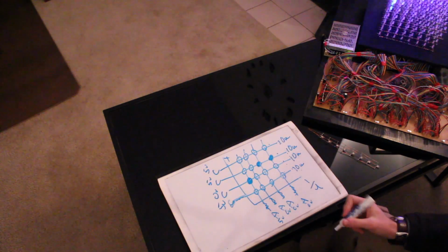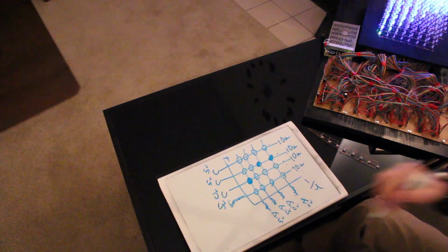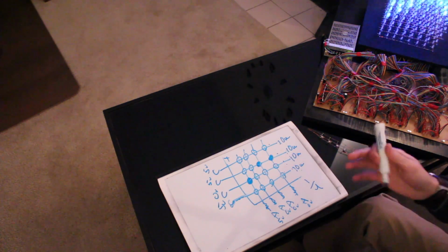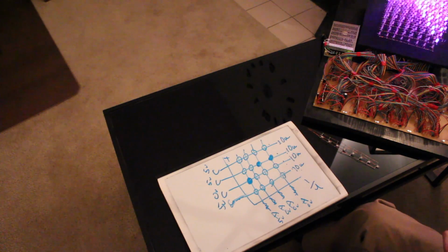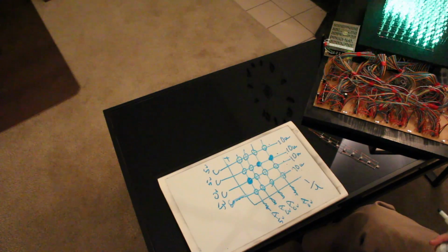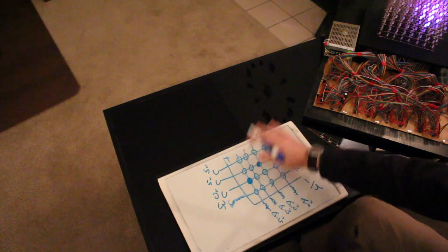And if you check the data sheet, you'll actually notice that there is a value in there for max current, and then it's proportional with some time value. So you can pulse them a little harder. And this is essentially how the cube works. We'll get into that a little bit more, but I hope this makes sense. And this is how we control things.